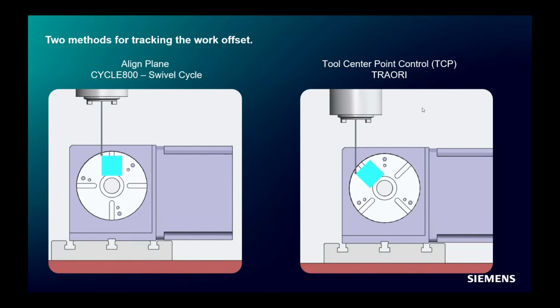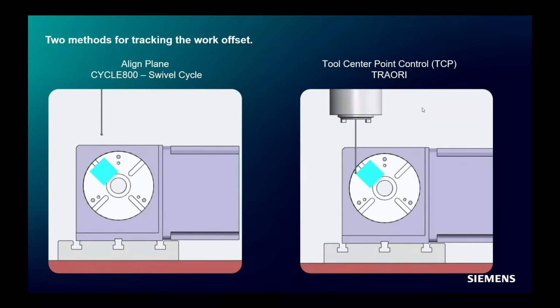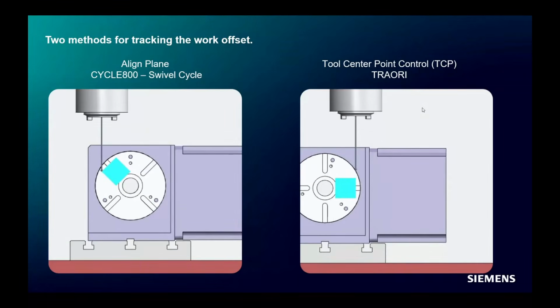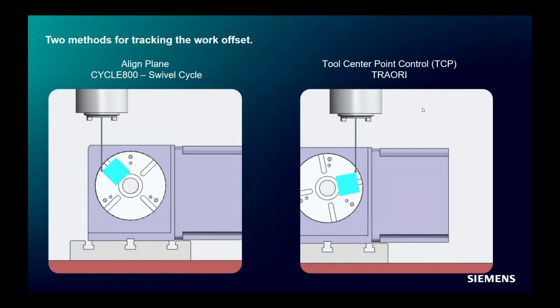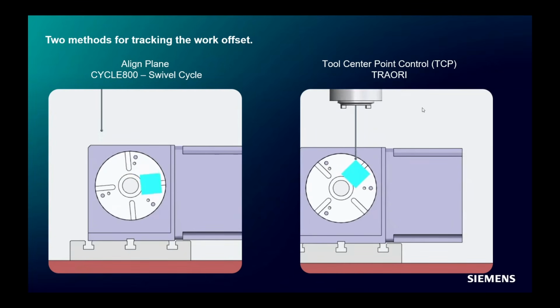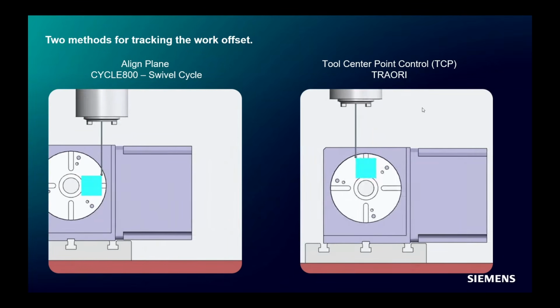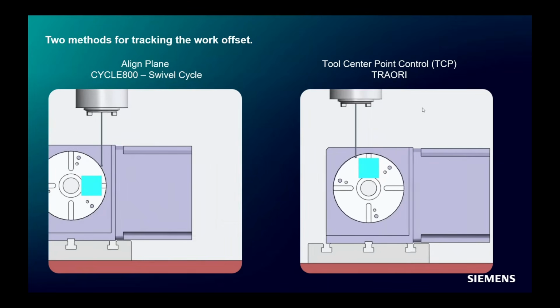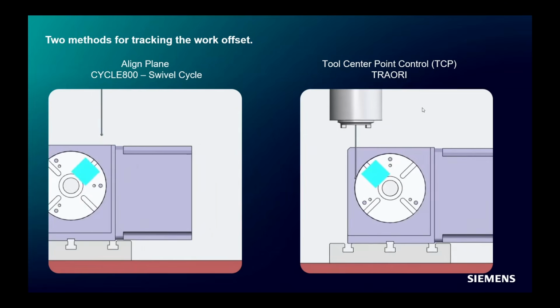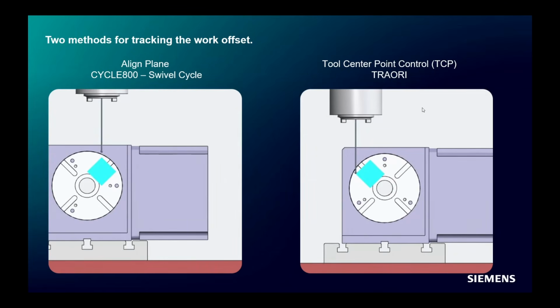Now, if we look at the behavior on the right, this is introducing tool center point control, what we would refer to as rotary. And in this case, as I start to move around, first you'll see the motion's a little different because we can track as we move between positions. But now look at the little Z move I made. Exact same effective program, but rotary or TCP keeps your coordinate system fixed on your initial coordinate system. So my Z is staying normal to that first face.